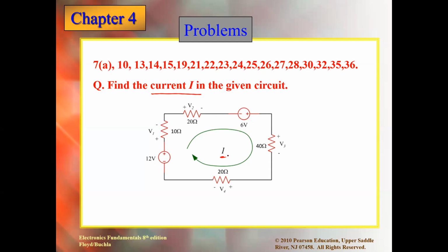See this one, you can apply the loop equation, the general equation. What is that? The algebraic sum of all the voltages is equal to 0. If you remember, I told you, you just need to consider the first sign. From any point you can start. For example, I want to start from here, going in the upward direction, then completing the loop. So what is the first sign of the drop of this voltage? Negative. Okay. So I will write 12.